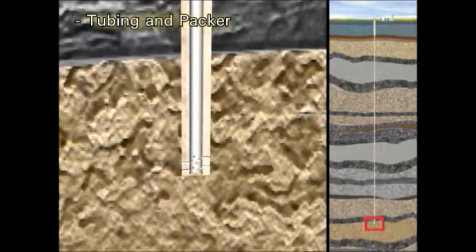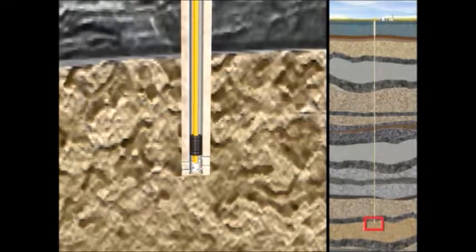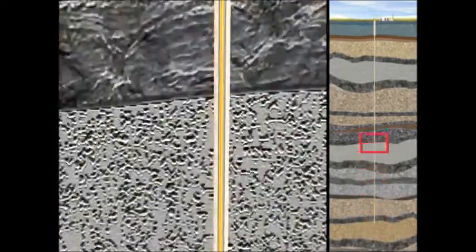A third layer of protection is provided by tubing and a packer. Tubing is installed inside the long string casing with a small mechanical device called a packer at the bottom. The tubing material and the packer are resistant to chemical reaction or corrosion from the injected fluids. The packer seals the outside of the tubing to the inside of the long string casing.